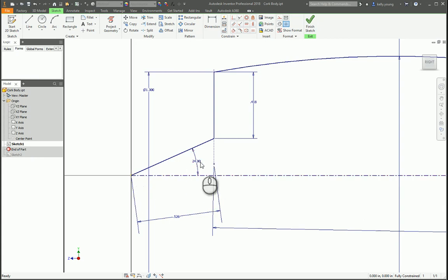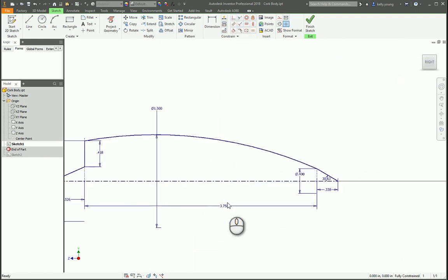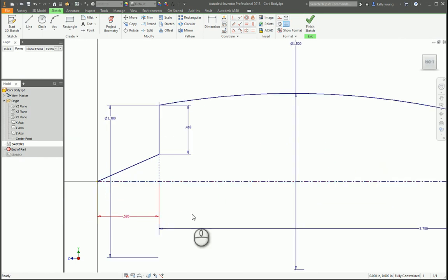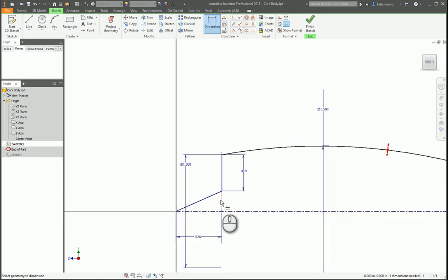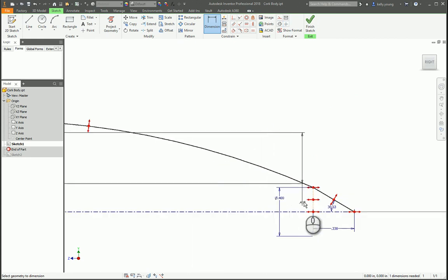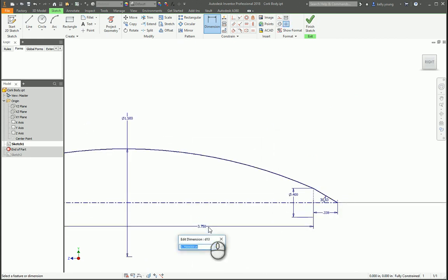So once you change that number, the rest of it goes up and down. So let's say if we delete this, put this point on that line, now our dimensions are going to be right, like this. Delete that dimension from this line to that line, 375.